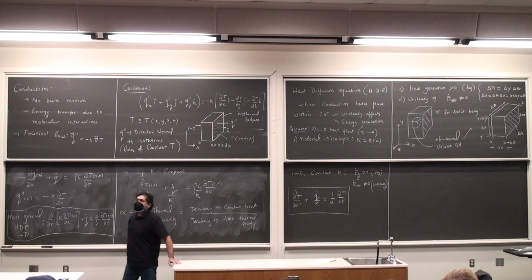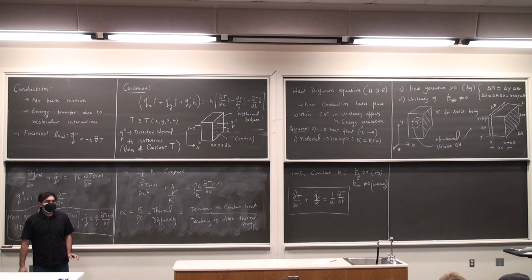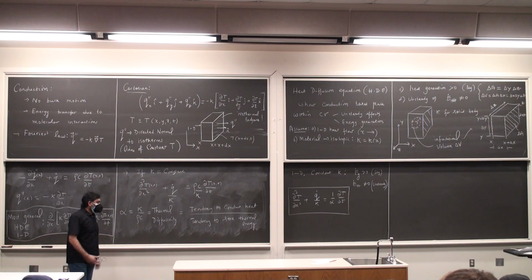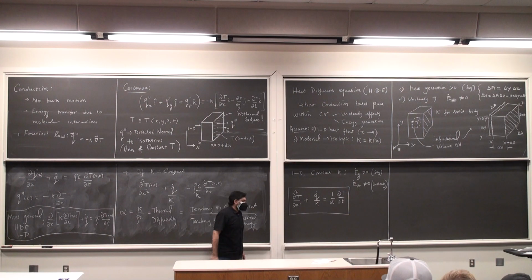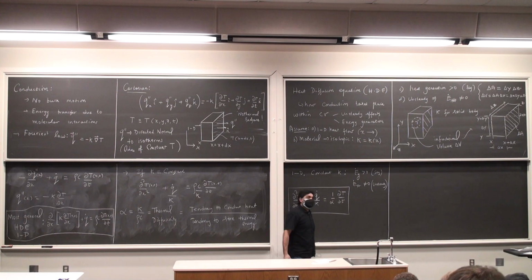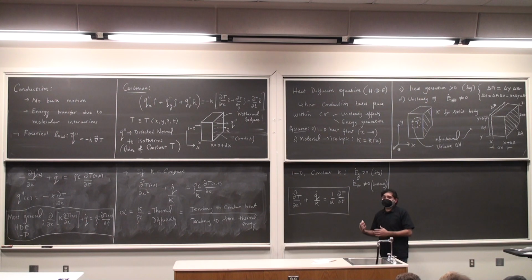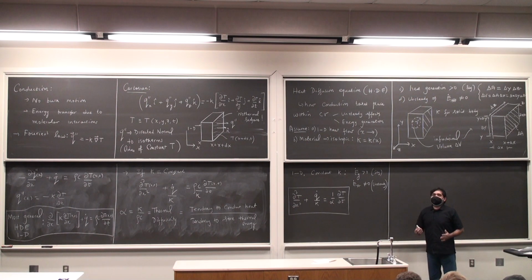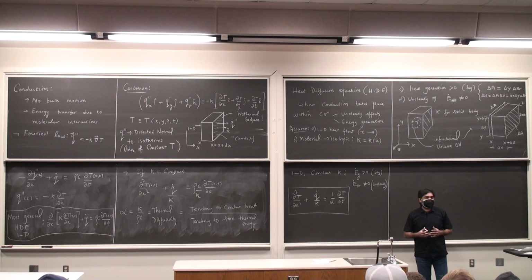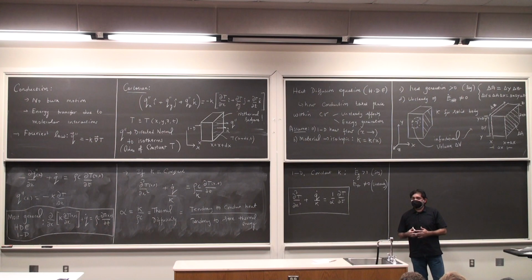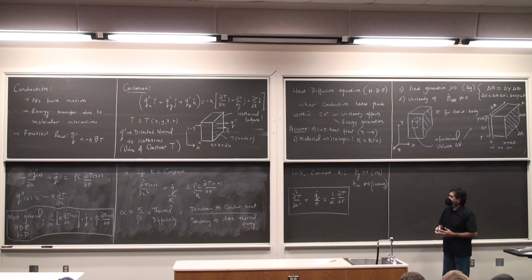And so you would have heard the term diffusion of heat. Right? What's the difference between conduction and diffusion? There is a very thin line separating the two. Diffusion can be categorized as any general heat transfer, but we are studying it from the perspective of conduction. So one way of thinking about diffusion is it is similar to unsteady conduction. Conduction in the presence of change in the stored energy within the control volume. Okay?